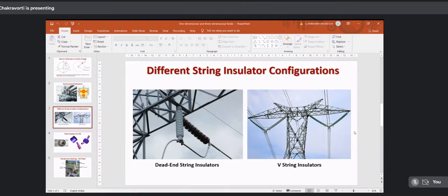Middle core will be steel reinforced and outside will be aluminum. So it is aluminum conductor, steel reinforced. Right. But they are also not one single conductor, right? They are called stranded. I think you have heard the term stranded conductor, because if I use just one cylinder, it is not mechanically very strong.